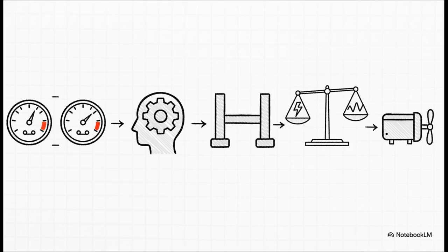A limiter steps in to ensure this slip doesn't exceed the motor's maximum torque range, which is absolutely crucial because if the slip gets too high, the motor enters an unstable region and just stalls out. Finally, by keeping the voltage and frequency strictly proportional, we generate the final command for the inverter. It definitely works, but as we'll see, it has its limits.